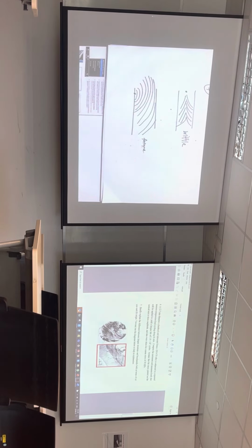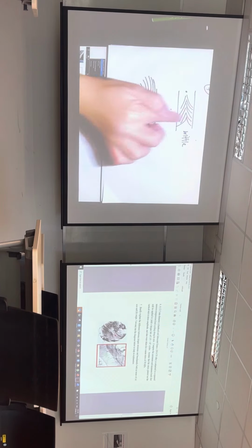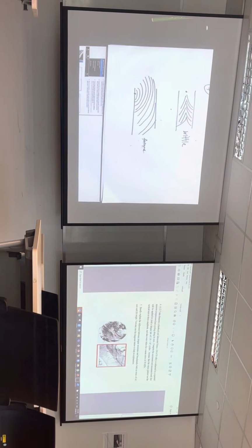This one that points back is brittle. So whenever you have a failed product, you take it out and take a look, and straight away you'll be able to say something about it already. Understanding the crack morphology, how the cracks go, will let you know which failure mode it is.